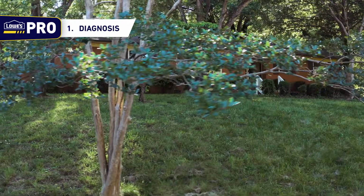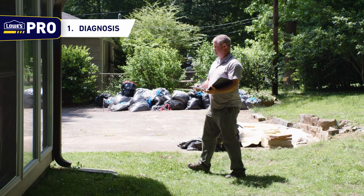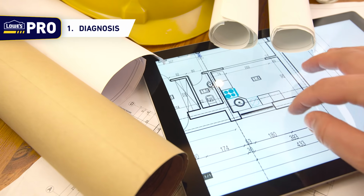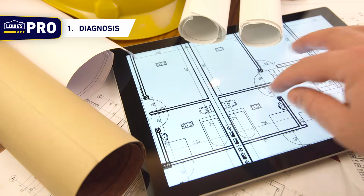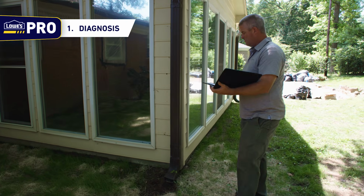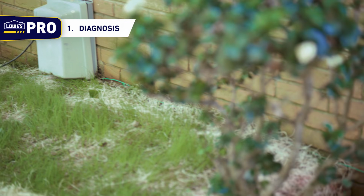Step 1. Diagnosis. The first step in any crawlspace remediation project is to do a walkthrough of the property and diagnose the problem. If you're able to, get a digital diagram of the floor plan from the homeowner or a footprint of the house and land information through GIS before arriving on the property. This will allow you to be sure that you are inspecting all potential problem areas when diagnosing the issues on site. Begin the inspection process by walking around the outside of the home and identifying any drainage issues, like downspouts emptying and draining into the foundation of the home, or any grading issues that may cause excessive water to enter the foundation.